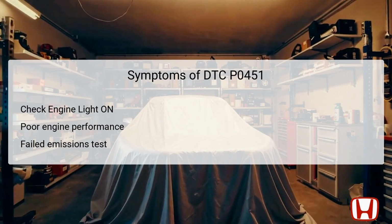When DTC P0451 is stored, several symptoms may manifest in vehicle performance. The most immediate and visible symptom is the illumination of the check engine light, CEL, on the dashboard. This warning alerts the driver that there is a problem that needs addressing. In terms of performance, drivers might experience issues such as rough idling or hesitation during acceleration due to incorrect fuel pressure management.